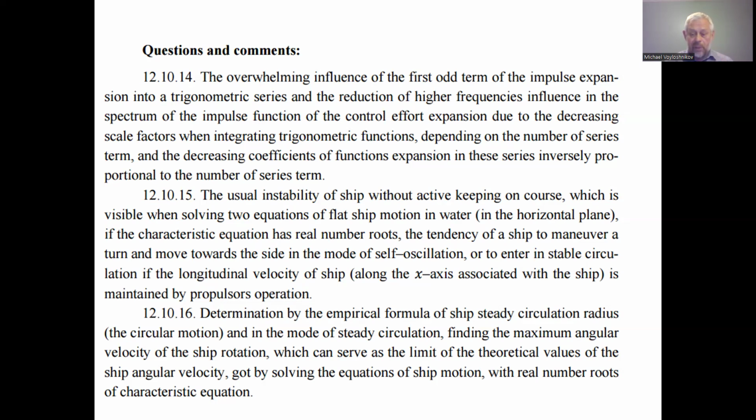In one of the previous articles, we considered the ship motion on the surface of still water with no controls, and we found that the ship does not possess the property of stability on course, and it tends to lose sustainability. It can have it, but only in the motion aside, to starboard or to port. Transverse motion could be stable within a definite concept of stability, if we consider stability as the self-oscillation of ship motion aside.